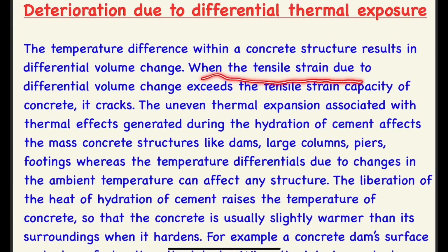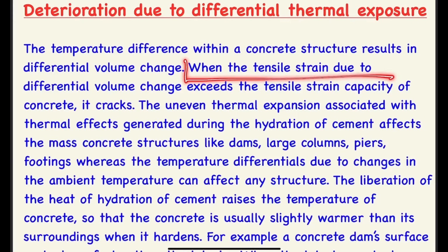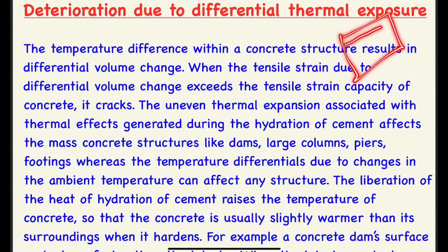When the tensile strain due to differential volume change exceeds the tensile strain capacity of concrete, it cracks. So we need to understand this point. This is a very important point. When the tensile strain due to differential volume change exceeds the tensile strain capacity of concrete, so there must be a tensile strain capacity of concrete. This is concrete. It must have some capacity, tensile strain capacity.